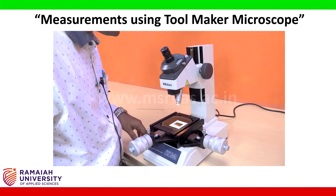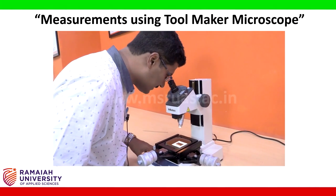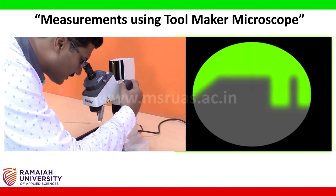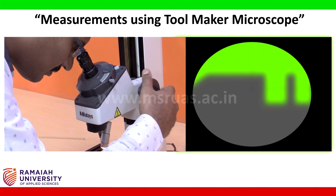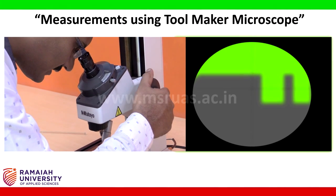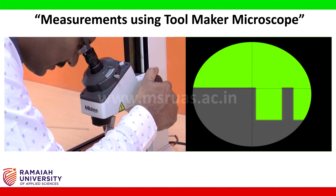After placing the specimen on the XY stage, next step is to look through the eyepiece and adjust the focusing knob so that one can see a clear object through the eyepiece. I am adjusting the knob so that I can get a clear image of the workpiece. I have got the clear image of the workpiece now.